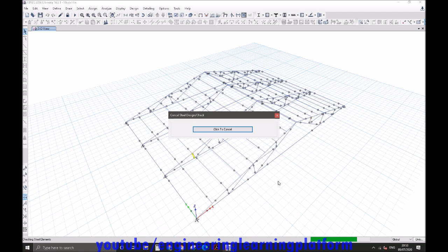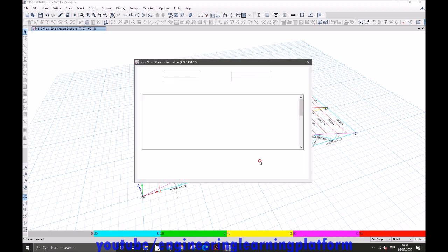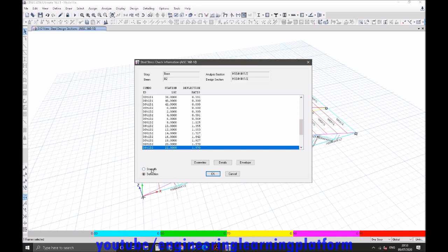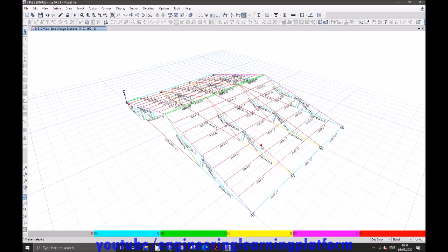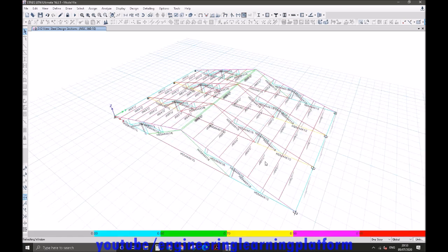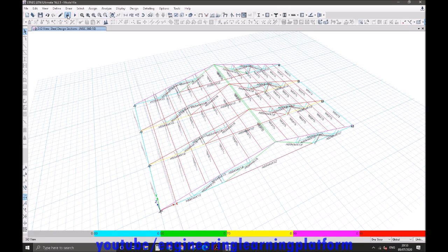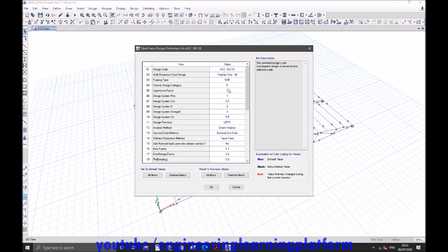In order to make it more realistic, we can assign the unbraced length at particular points if the purlins would still be failing like they are. So we'll change the unbraced length factors. So still a few of the members, or I'd say all the interior trusses, primary chords and the bottom chords, are failing as I expected. So in order to keep uniformity, I'll keep the size of the external truss and the internal truss, top and bottom chord the same.